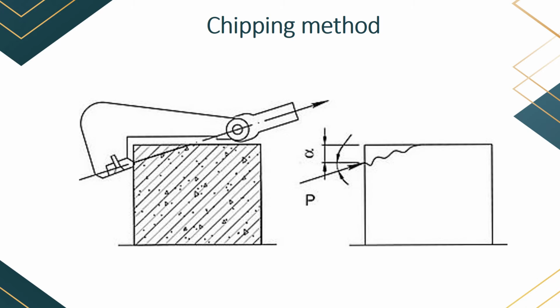Currently, there are two ways to perform tests in accordance with these methods. They depend on the types of research devices. The first one is used for structures made of concrete, reinforced concrete, that have more than one adjacent face. In this case, the device is attached to a structure by the type of a clamp, being fixed on both sides of a structure. Through a manually driven mechanical device's element, a load is applied at an angle to the surface of a measurement area.